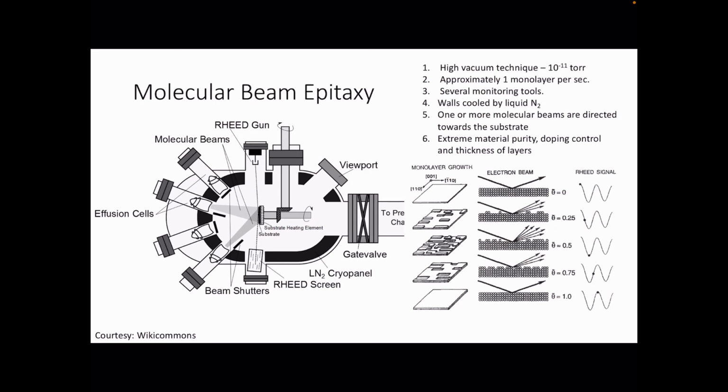Molecular beam epitaxy is another way in which you can grow really thin layers, something whose thickness is lesser than probably a few nanometers, right? Like 10 nanometers, something lesser than 10 nanometers. The idea is they will grow monolayer by monolayer. You have several sources which can be independently controlled. So what they do is they start passing the independent metal sources and then the gas source in very small fractions, and they will let it grow by a layer by layer method.